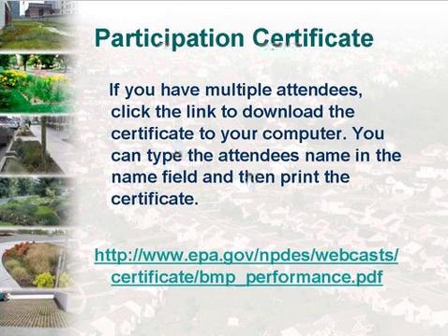Yeah, and I'd like to add to those comments that by using a treatment train approach where you focus on specific unit processes to deal with specific parameters one at a time, you can minimize that transfer of pollutants to the groundwater by focusing on sedimentation processes perhaps up front, or particular vegetation that can uptake those toxic contaminants before it moves on to another, perhaps infiltrating, BMP to deal with another set of parameters.